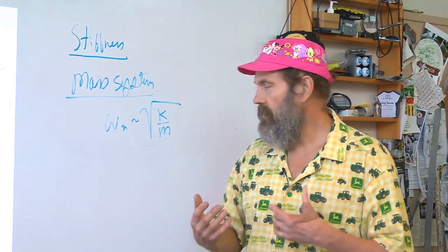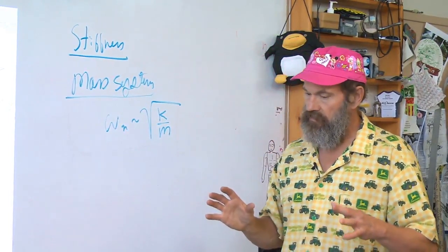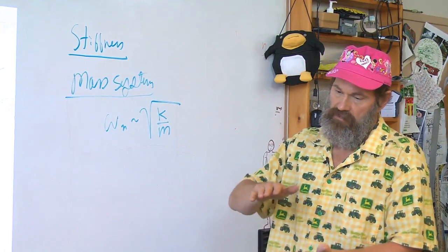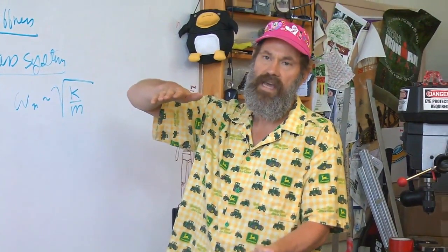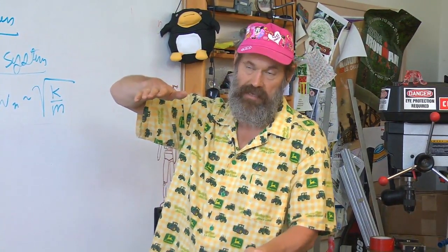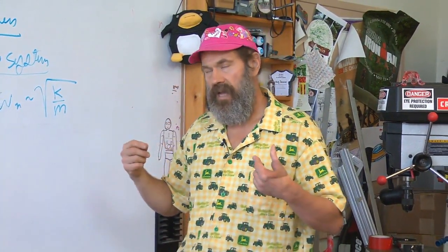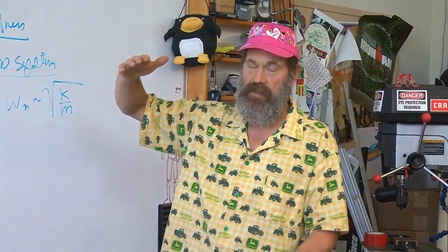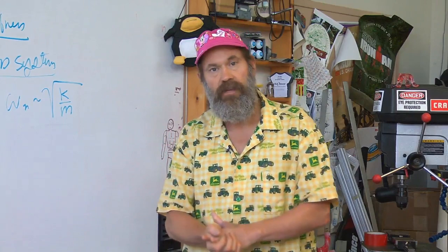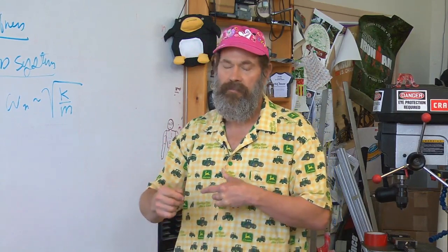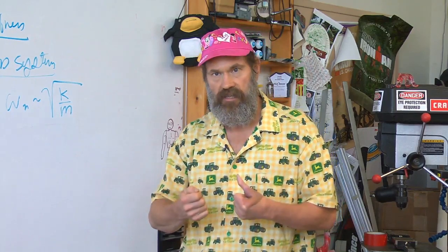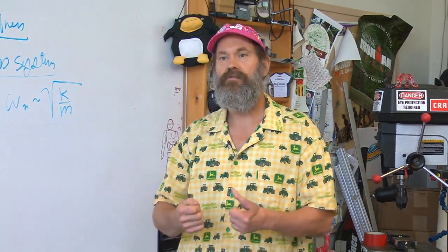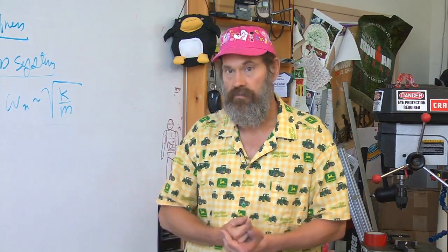And as long as you're designing your structure with the intent of using the neutral axis theorem to keep most of the mass away from the neutral axis, like for example, an I-beam, and you have provisions for how you can add more mass far away from the neutral axes of the members or add in diagonal stiffening elements without obstructing the motions that are intended, you at least have a strategy or countermeasures for the risk of natural frequency too low.